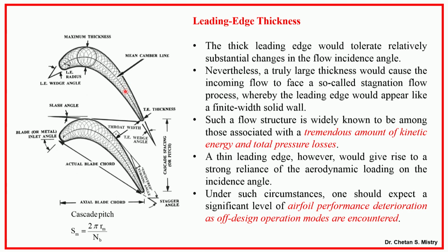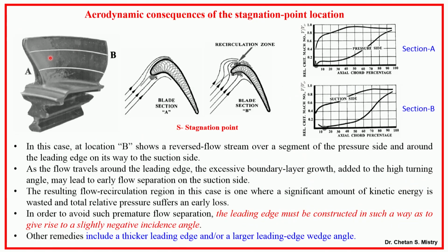Still it is having acceleration, but on the downside after this throat we will be having deceleration of the flow. So, larger will be the thickness, more will be the acceleration you will be getting near the leading edge. If we are talking in terms of Cp distribution here, suppose this is my maximum thickness, you can understand what we are talking in terms of my suction surface.